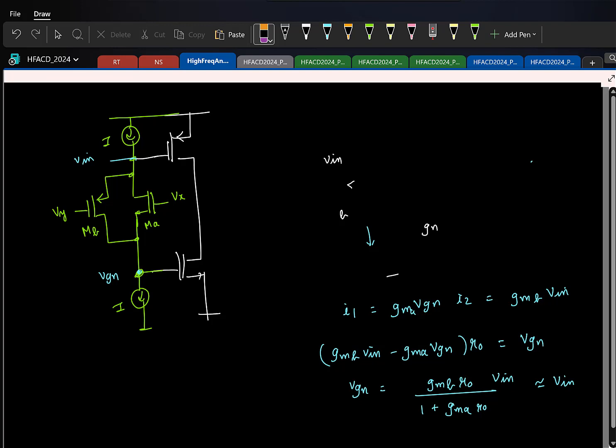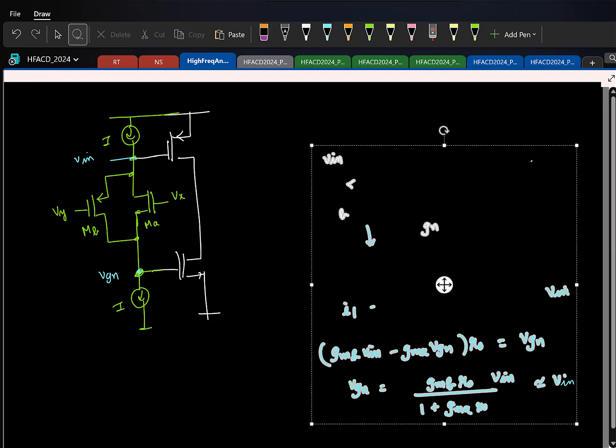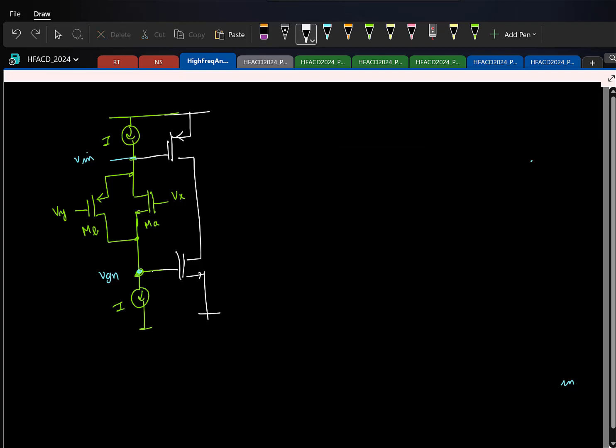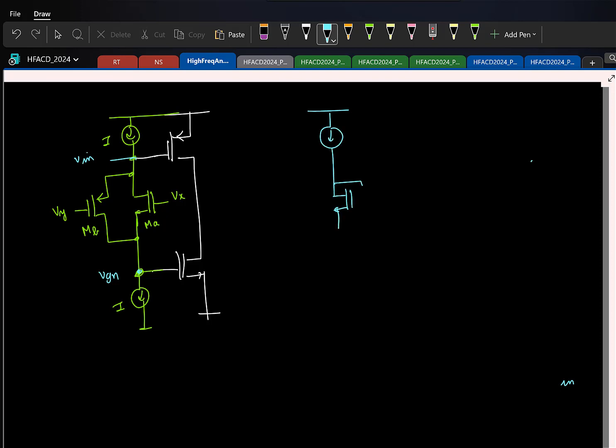Yeah, if you have diode connected stuff, let me, let's say you mirror the same current here and then do 2 diode connections. This voltage is 1 VGS, which means this will be 2 VGS. So as long as you make sure that the NMOS transistors are all matched and similar, this will nicely work. So this you can go and connect to Vx.